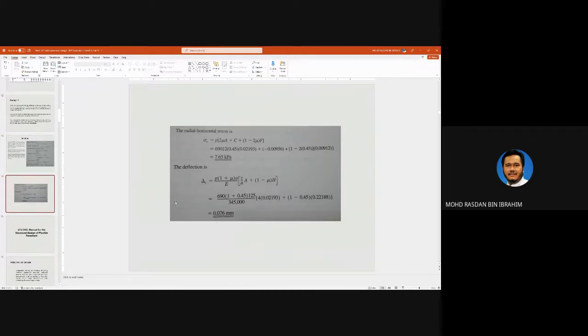That's why the thicker the layering is, the better it is for the subgrade. If you have a weak subgrade, but if the subgrade is too weak, you cannot basically use the subgrade. You need to remove it or do some kind of treatment before you can actually design the pavement on top of it.